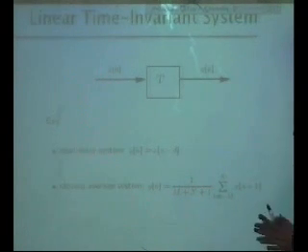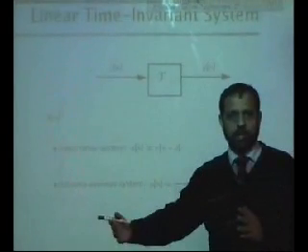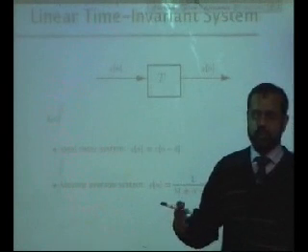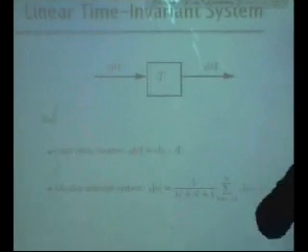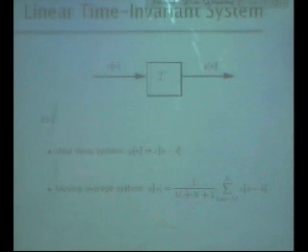Wherever you are standing, I ask you to add the next 2 samples and previous 3 samples. Then you move, add the next 2 samples, previous 3 samples. The system will still be linear and time invariant, right? But usually we don't have future samples. So in 1D signal processing, you avoid using the future samples. In image processing, you can use future samples because you acquire the entire image.